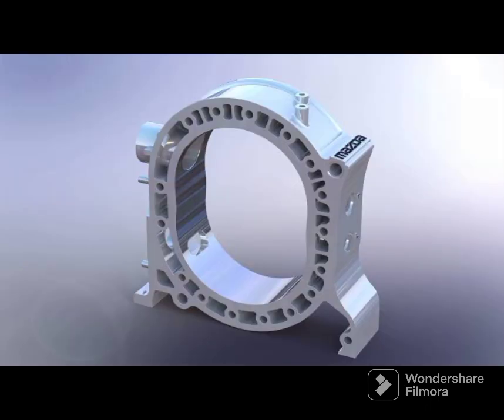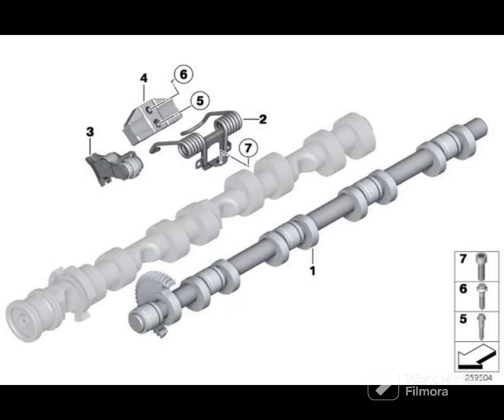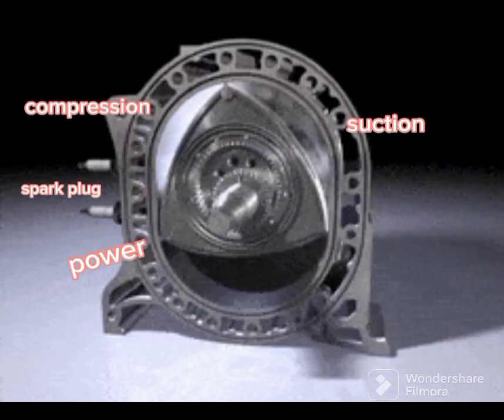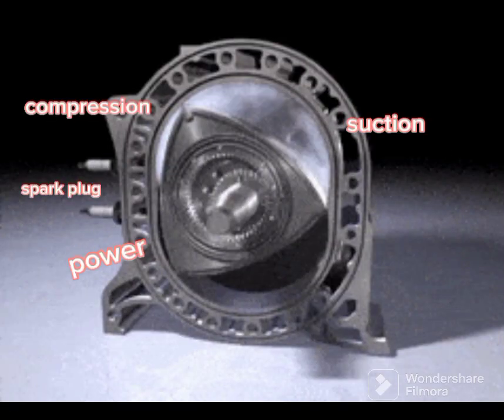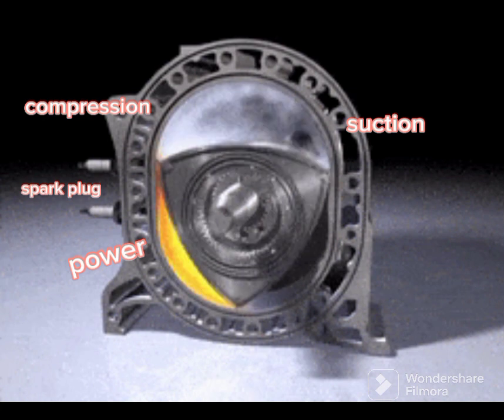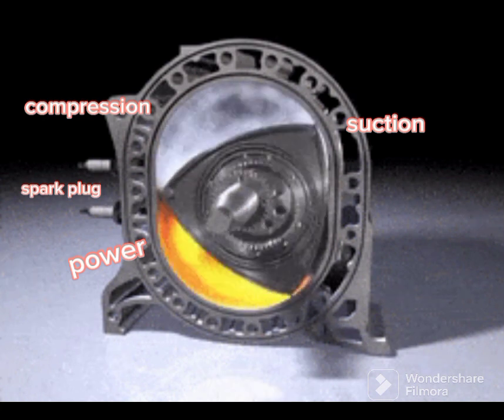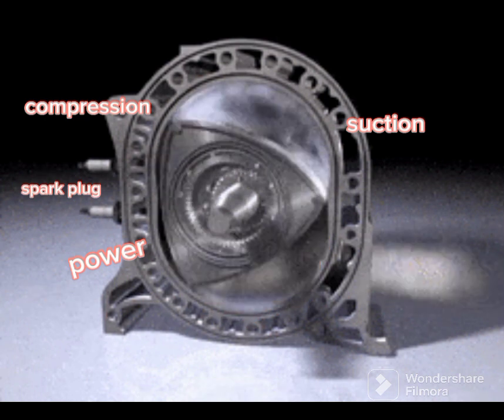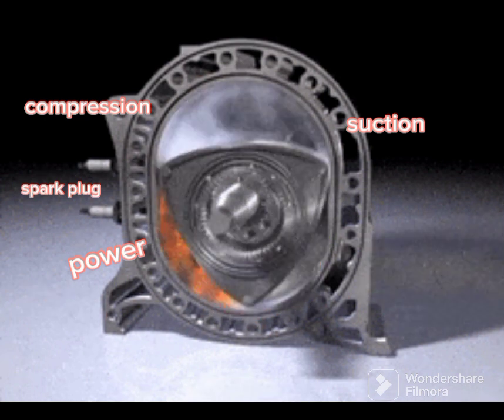The eccentric shaft is connected to the rotor and converts its rotational motion into the reciprocating motion of the engine's output shaft. As the rotor rotates, it passes through three different zones: the intake, compression, and combustion exhaust zones. Each of these zones is created by the geometry of the rotor and housing.